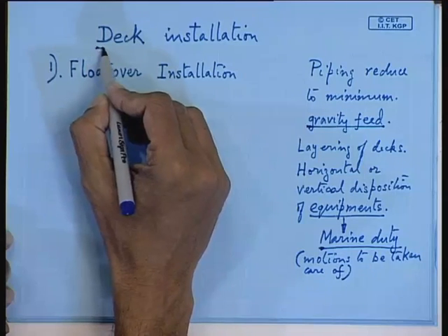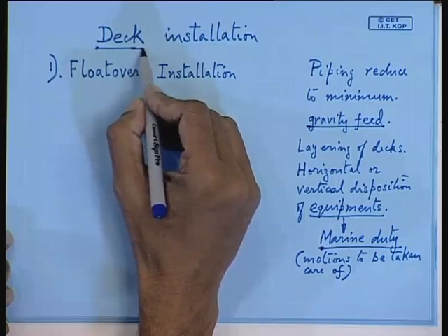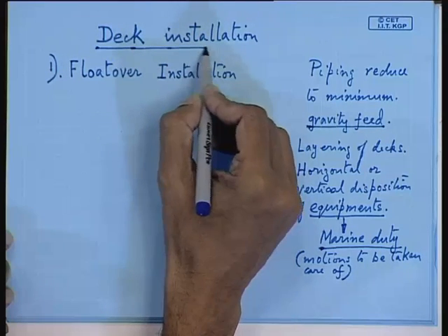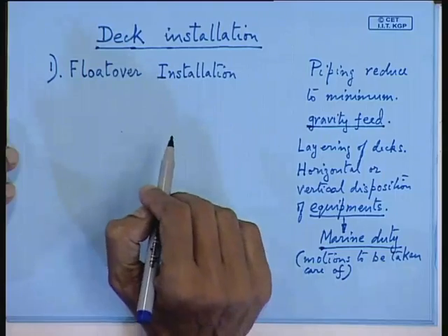That is going to come on the topsides. So, topside layout is not very easy, and after you have done all this, the deck has to be installed, isn't it? Normally, there is the underwater truss that is built separately in the shipyard, that is floated out, or it is carried by the barge, and then it is appended. So, decks are normally positioned on top of the platforms after the underwater truss has been installed and properly secured on the seabed. Now, how are you going to install that deck?